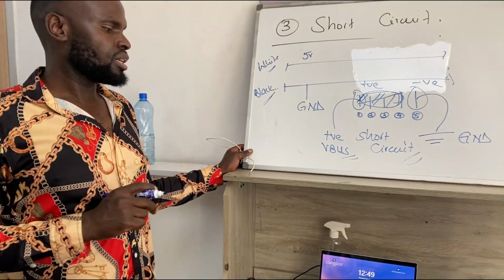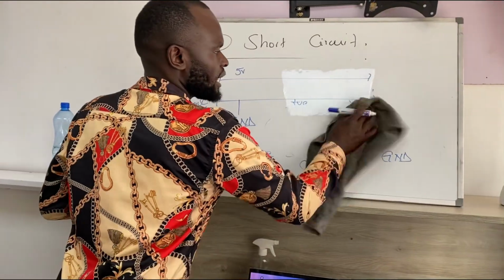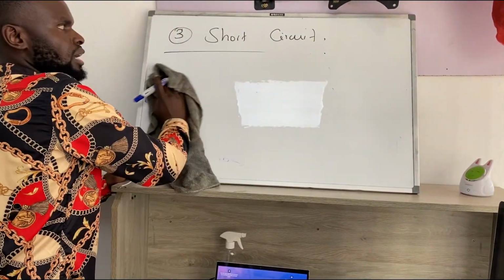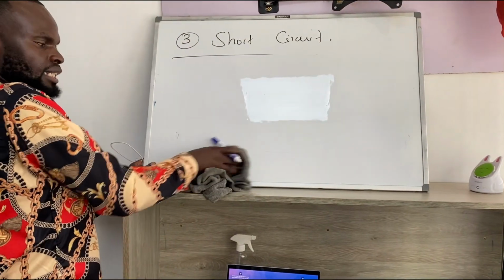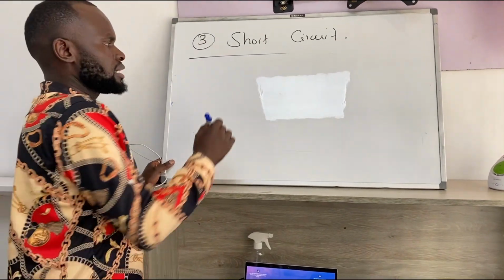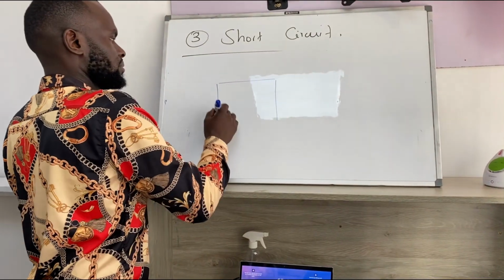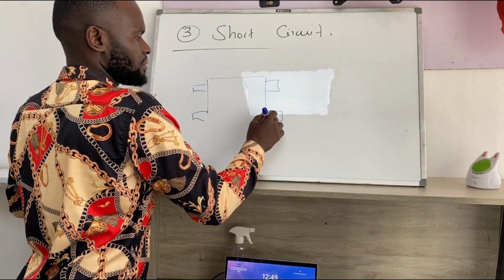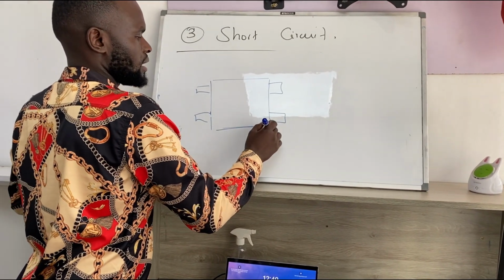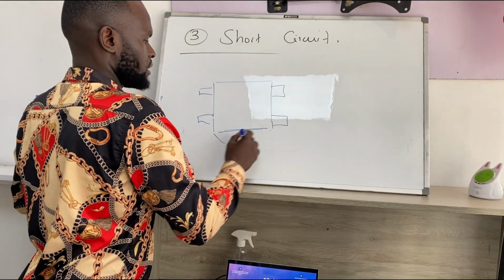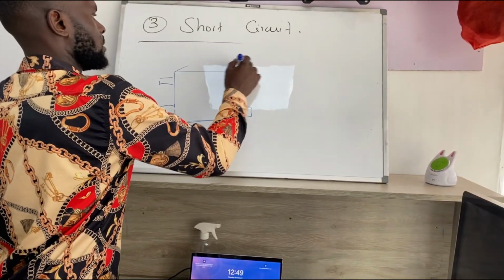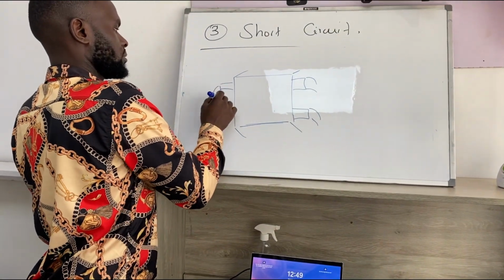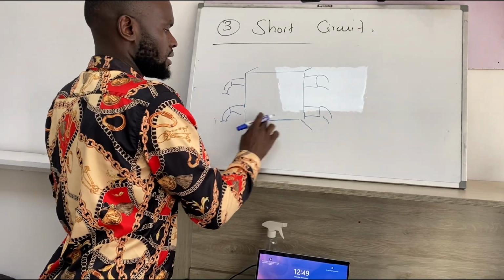So if by any chance you put excess solder or tin while putting a charging port, you're going to create a short circuit. See, charging ports are made like this, with the charging pins by the end, the holding pins. If I try to create a 3D image of a charging port like that, you'll have pins here.